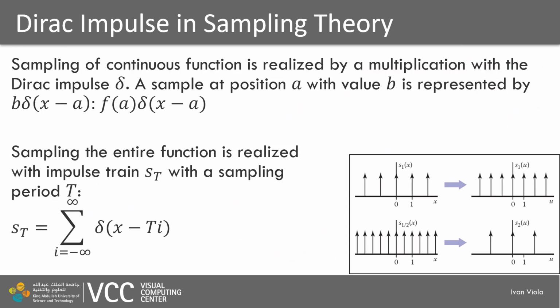Now we know that we can transform the signals of known reconstruction filters into the frequency domain. So instead of convolving in the spatial domain, we can actually multiply with these reconstruction values in the frequency domain. And that multiplication can be carried out much faster, or can be much more intuitive regarding what is happening with the signal.